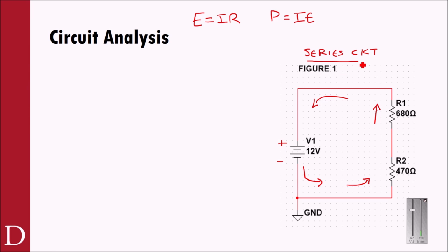In this case, because it's a series circuit, it's going to hit all of these various components. So what you need to be able to do in this class is solve for total current, solve for a current through a component, voltage, wattage, any of that stuff. Let's give you an example here. We know that the total voltage is equal to the total current times the total resistance. That is Ohm's law right up here. And in this case, total voltage is easy to come up with.